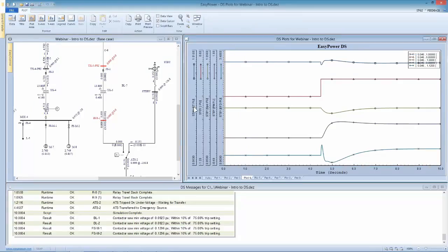and what we're looking at here is the terminal voltage on the standby generator, where it comes online. It accepts the switch over of the voltage to the standby condition. The current pickup, the speed pickup, or impact on the speed. The field as the load starts to stabilize, and it seems to recover, transferring over that load within a fairly short period of time.